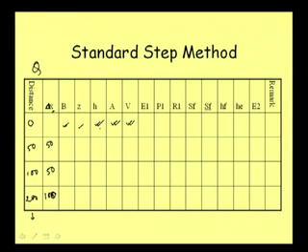So, when we know h and v, then we can calculate the energy at section 1, that is h1 plus v1 square by twice g. That we can calculate here. Okay. So, this is known.